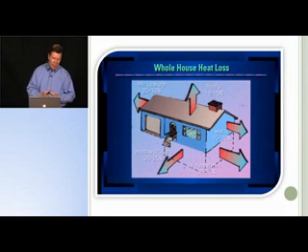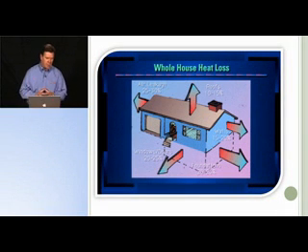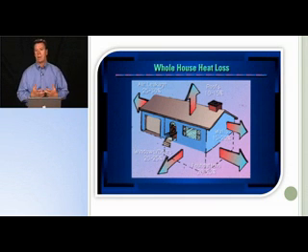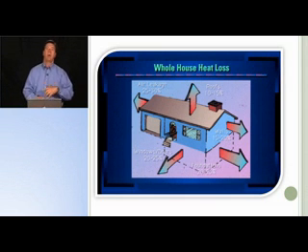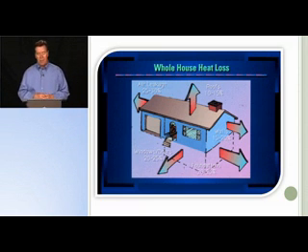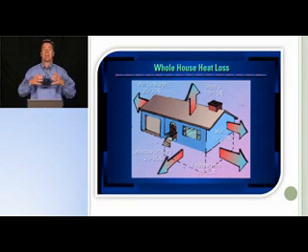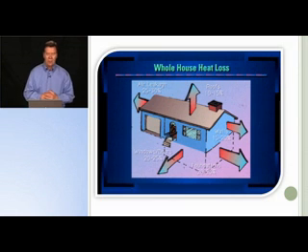In this section, we spent obviously some time talking about how heat transfers and so forth, but now we're going to apply that to a typical home. We look at older homes like we're going to be weatherizing, and we analyze where these homes lose their heat. We're probably looking at about 25 to 30% of their heating and cooling costs are due just to air infiltration, air exfiltration out of the building.